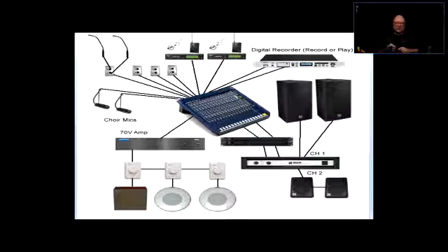Basically it has two plates in proximity to each other, and as you speak, the plates vibrate. That means the capacitor made out of those two plates changes its capacity. When it changes the capacity, it changes the resonating frequency, and certain electronic circuits sense that change of capacity.